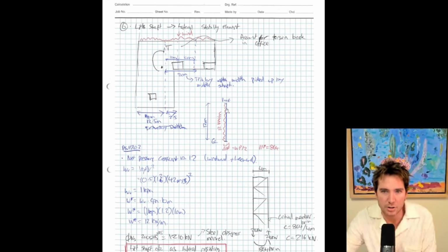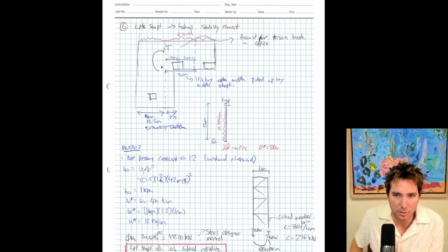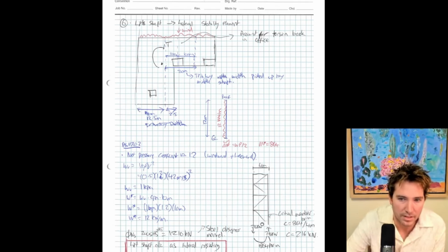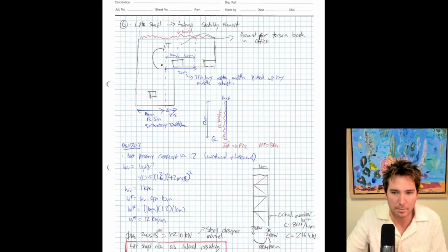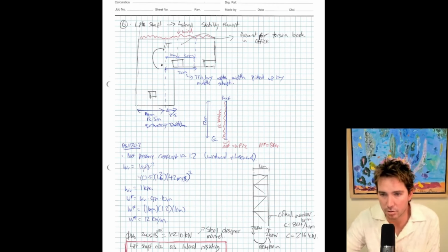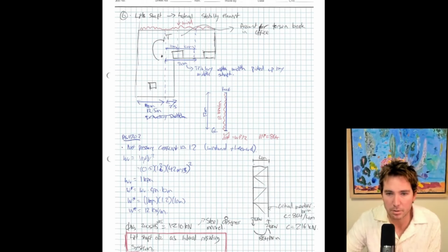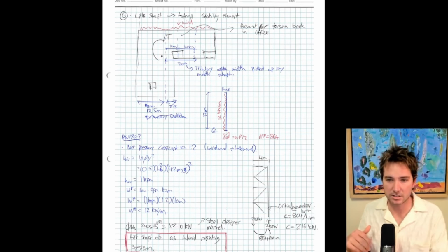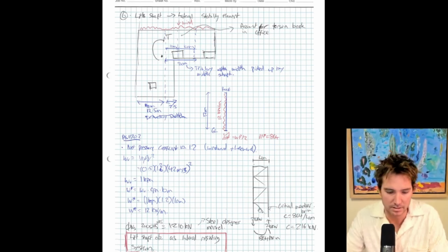Then I treat it like a cantilever, where I just say max bending moment is WS squared on 2 to get 864. Then from that, divided by my lever arm to get max tension and compression at the base, which is going to be my critical member for my braced frame, because a steel member in compression is going to be more critical than a member in tension. So that's how I identify the critical member here. Check that for compression, and because it passes in compression, my 200 SHS, I know that my steel frame to account for those wind loads that we've worked out here is okay.